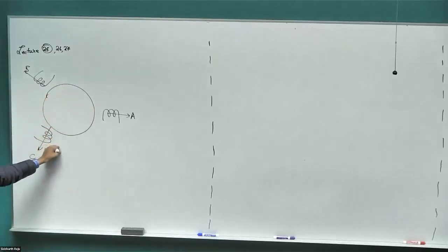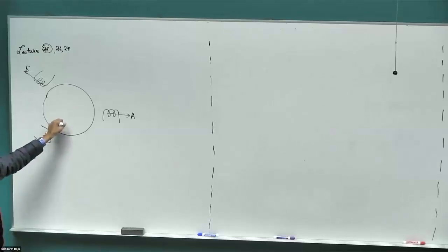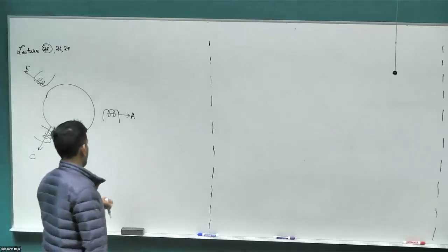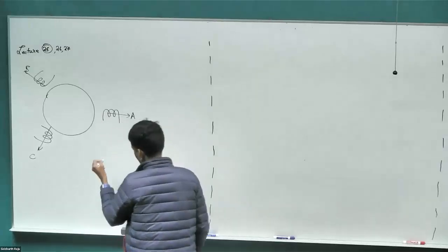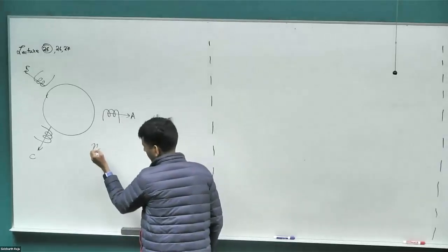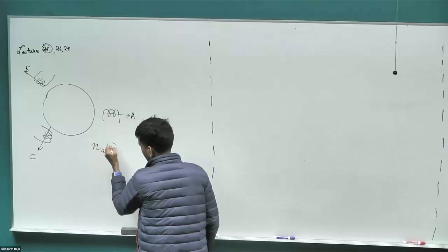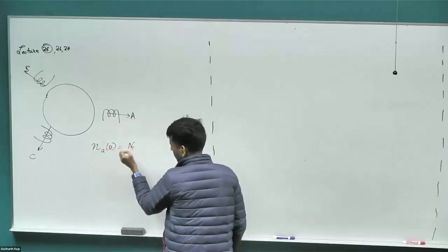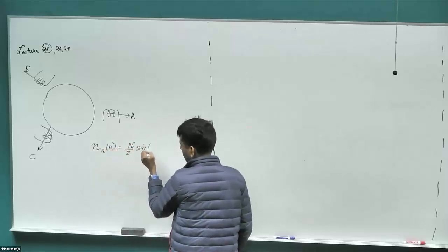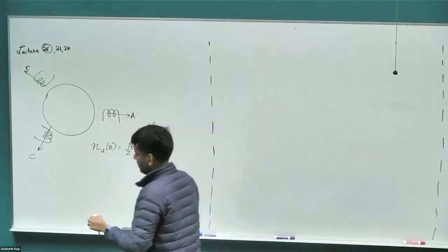The structure remains exactly the same whether we go to a permanent magnet motor or an induction motor. We are going to retain the stator structure. The only thing that will change is what we are going to put on the rotor in the induction motor. So once we have this, we have our expression for our conductor density distribution, Na of theta, which was N divided by 2 times sine of theta. Let's look at just the 2-pole case to keep it simple.